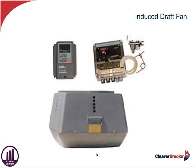Now, in some cases, especially where I've got a retrofit and I've added a couple of boilers, I've kept the existing breeching, and I don't have money to add any more to it. I know I can make this work if I put in an induced draft fan. Those induced draft fans can either be mounted in the vertical stack, as you see here, or in the horizontal, and thereby overcome the resistance to flow mechanically, driving those products of combustion to the stack and up and out. So that might be another option.